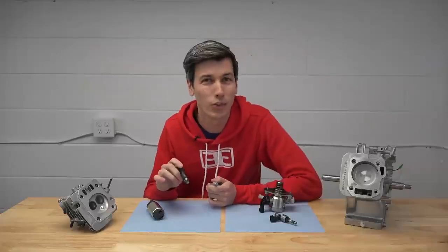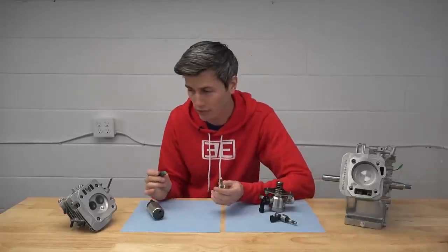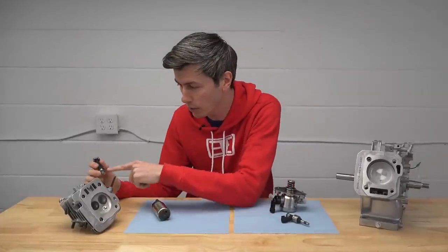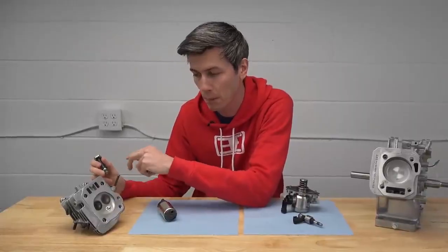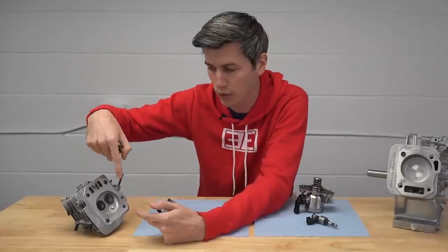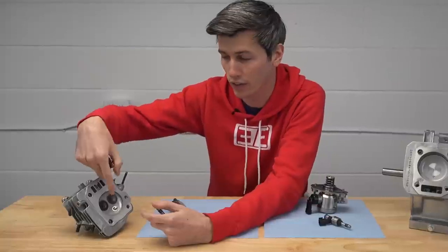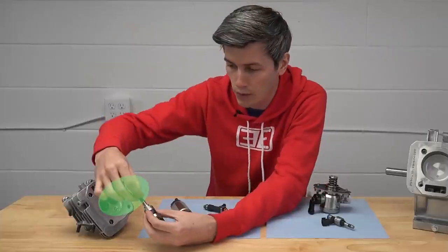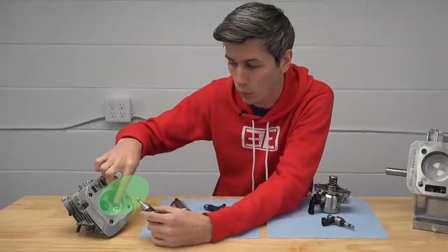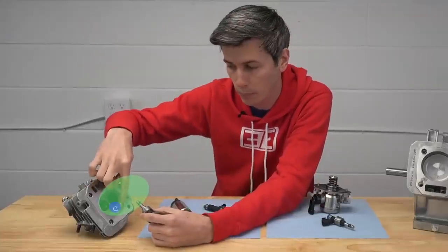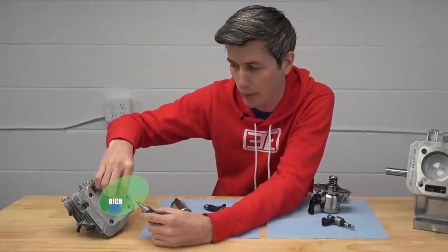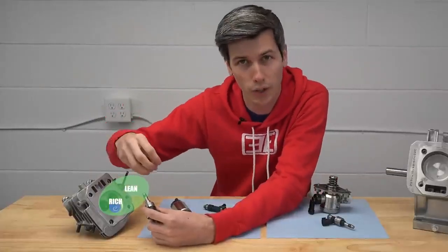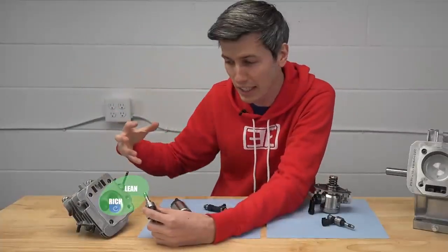Another clever strategy is to use a stratified air-fuel mixture. So what does this mean? Well, let's say we're trying to operate as efficiently as possible. So what we do is we use our port injector, we spray some fuel in, but it's still running very lean. So the air-fuel mixture that ends up within the cylinder, there's more oxygen than there is fuel to burn. And so in order to ignite that lean air-fuel mixture, we spray a bit with the direct injector right beside our spark plug. So right beside the spark plug, there's a little pocket of rich air-fuel mixture, and then everywhere else, it's very lean. And so the spark plug ignites that rich air-fuel mixture, and then the rich air-fuel mixture ignites all of the lean air-fuel mixture.